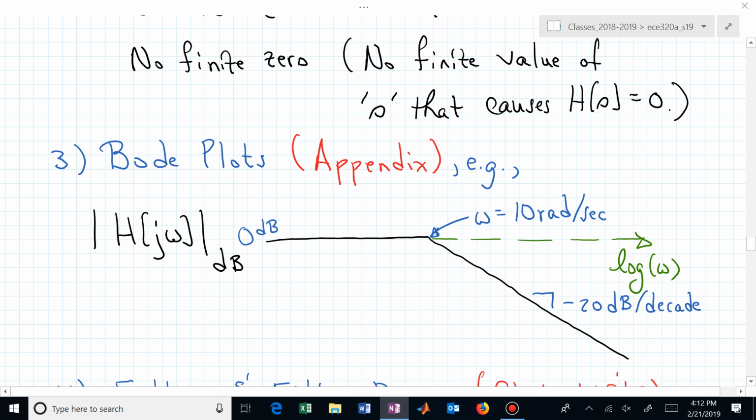That now takes this magnitude in a logarithmic sense, just like we've done the frequency. Looking at it in log or in dB allows us to take the logs of these amplitudes, and that allows us to add them up. A product of A times B, we take the log, it's like the log of A plus the log of B. We get to add things when we take the logs.